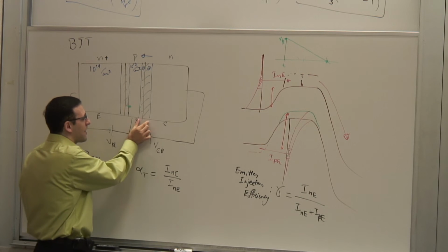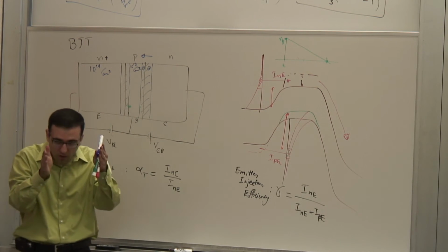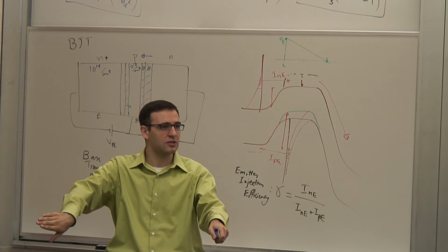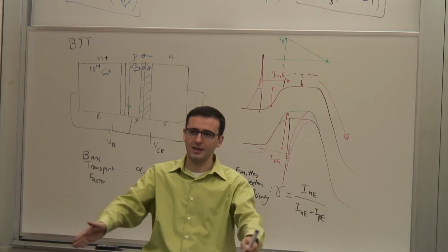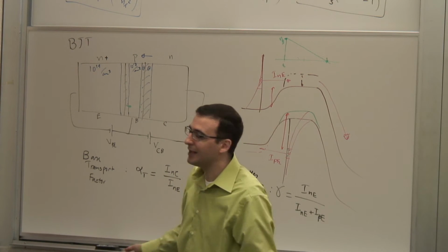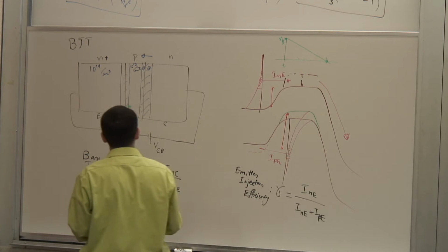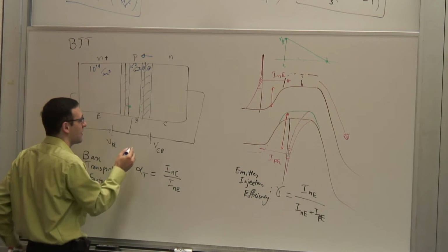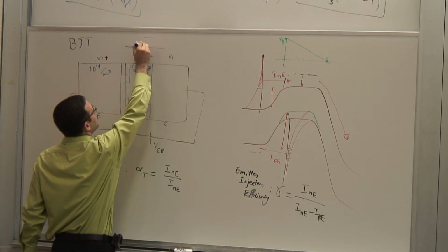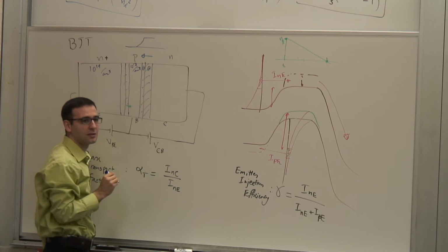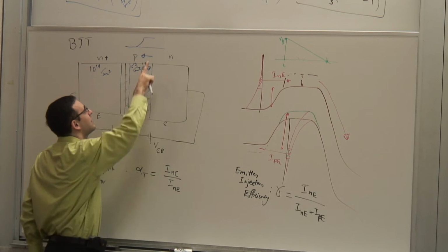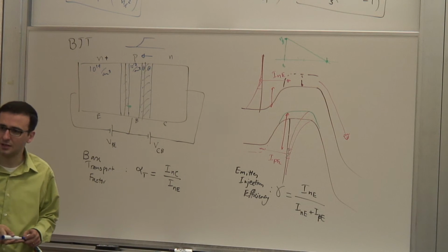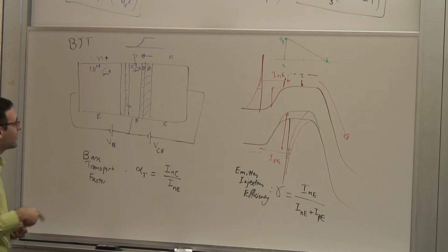Back to the assumption that this depletion region has very hard boundaries, right? So up to a certain point, you've completely depleted that region of charge, and beyond that, you have nothing. In reality, first of all, this depletion region is extended, but it's a gradual process, right? So it's not black and white. Up to this point, you're highly depleted, and then gradually you're reducing the depletion region. And in this residual part, in this tail, you still have electric field, right? So there is a little bit of electric field.